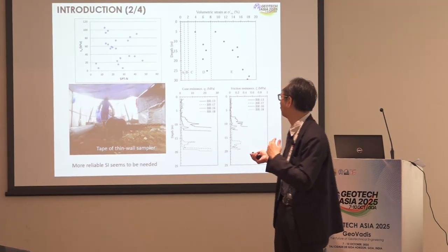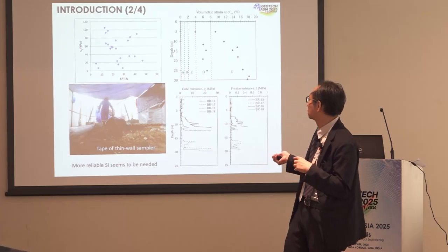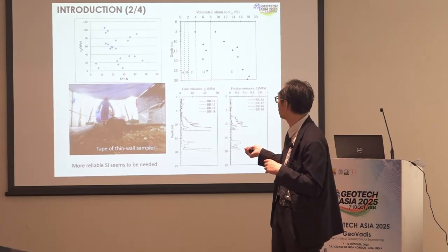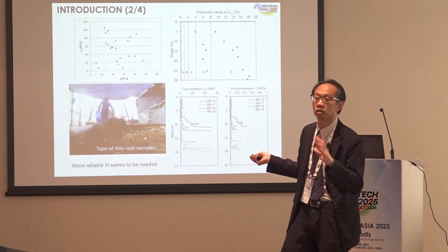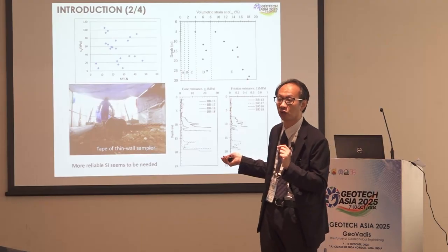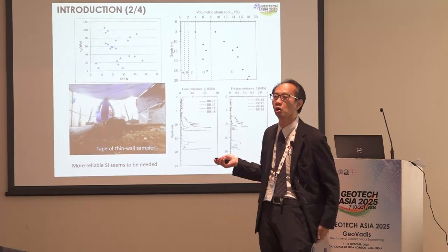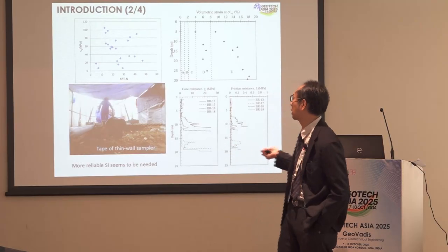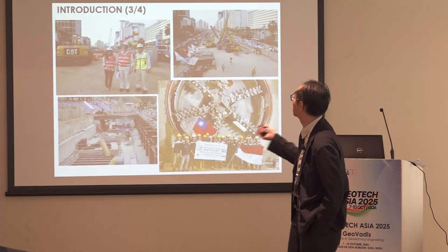Also we look at the CPT result and understand that deeper than maybe 8 meters below ground surface level, the soil is actually quite stiff. So this gives us confidence that we have to do more tests together with CPT to get more reliable test data. That's what the site condition has.